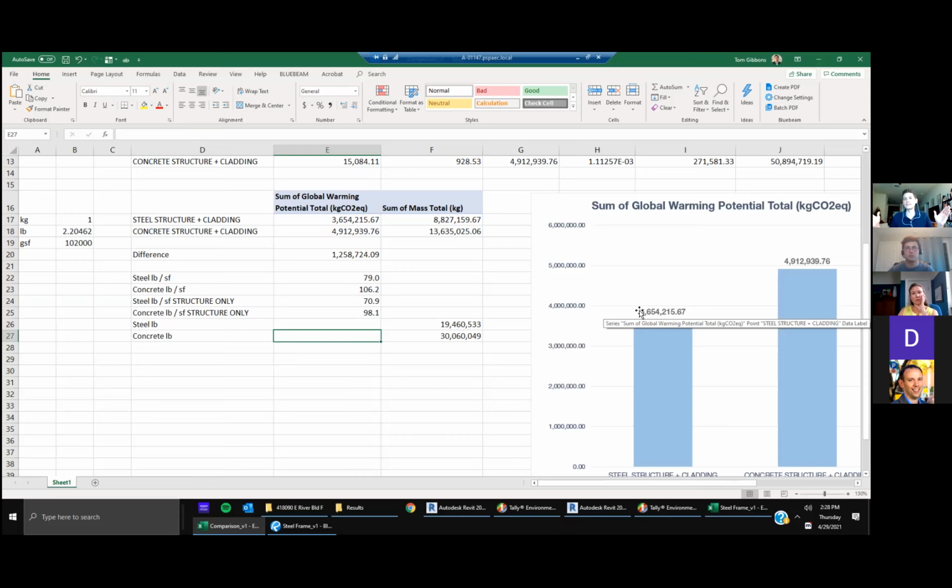If you move a column in 5 feet so that you can get people closer to the window, great, client's happy. Well, I'm sitting in the room like, wait a minute, your slab just went from 4.5 inches thick to 8 inches thick. And that has literally jumped us up millions of kilograms of CO2 over the 7 stories of this building. So I don't know if that's a good answer or even close, but that's what we're trying to do.